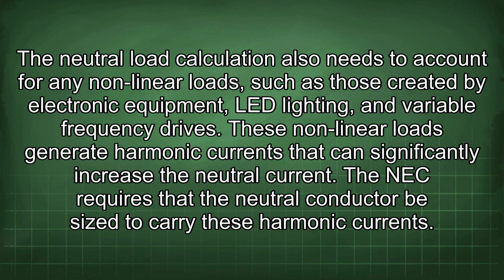This reduction recognizes that it is unlikely that all the unbalanced loads will be present simultaneously. The neutral load calculation also needs to account for any nonlinear loads, such as those created by electronic equipment, LED lighting, and variable frequency drives. These nonlinear loads generate harmonic currents that can significantly increase the neutral current. The NEC requires that the neutral conductor be sized to carry these harmonic currents.